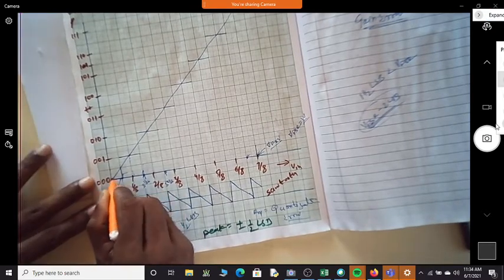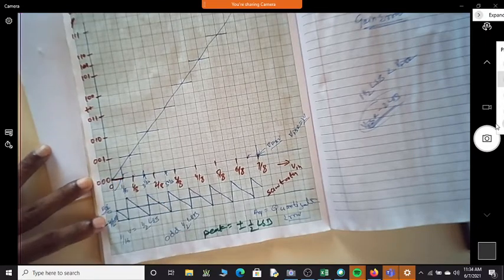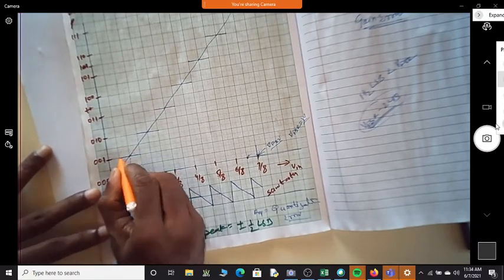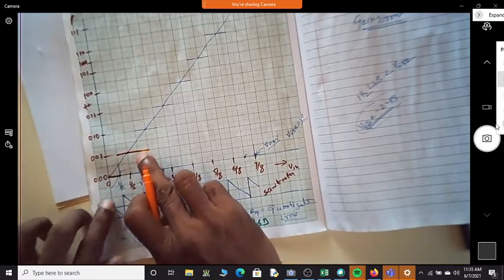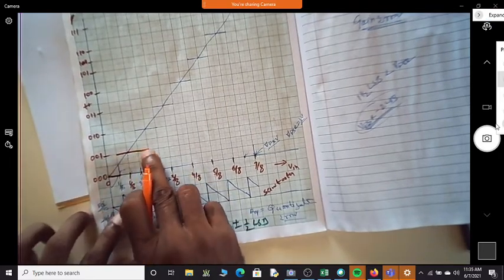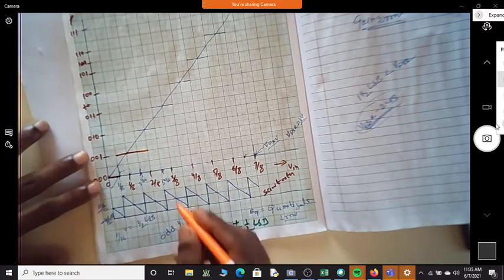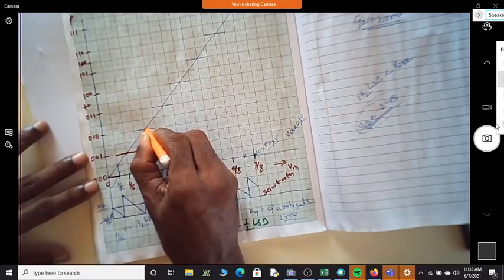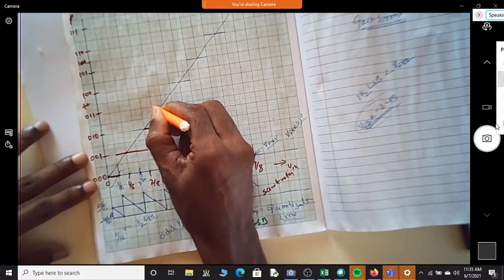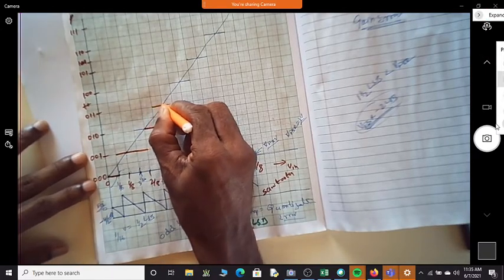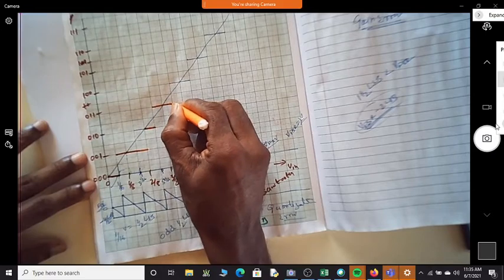This is fine. This is as per the ideal one. Whereas the second one has slightly extended. See now, this is not stopping here. This is going another half LSB more. Just half LSB. But the next one is starting from here. It is going till 1 LSB up.